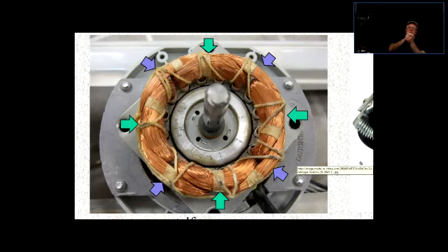With the DC motor, you have brushes, so you have mechanical parts because the brushes are brushing against the commutator connections. So you have mechanical parts rubbing against each other. That means at some point something is going to break, something is going to get used. When it comes to an induction motor, if you just use it as a motor, you can use a squirrel cage.